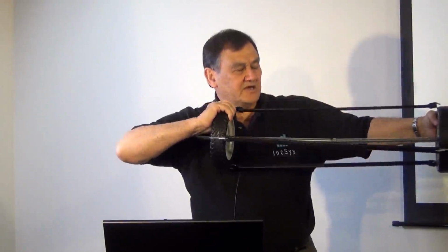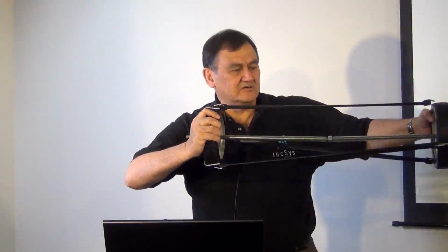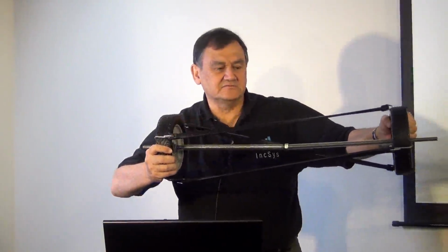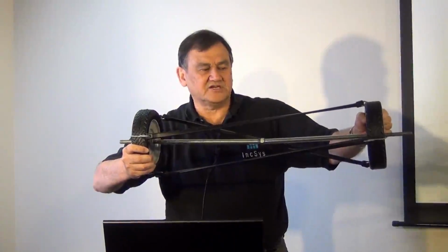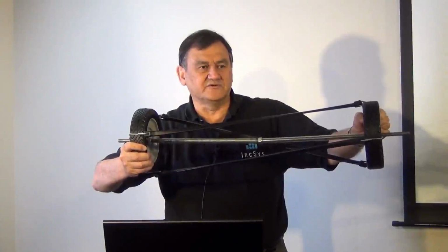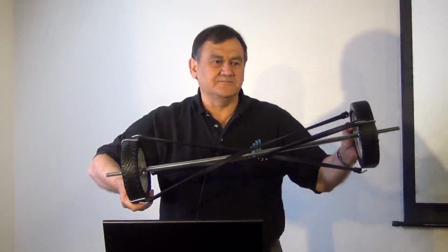And notice, as I advance my angle, the voltage at the middle of the line is dropping. I get to 90 degrees, and my voltage, I could actually work it out, it's 0.707, 1 over root 2 at 90 degrees. But then look what happens when I go to 180 degrees. My voltage at the middle of the line has gone to 0.